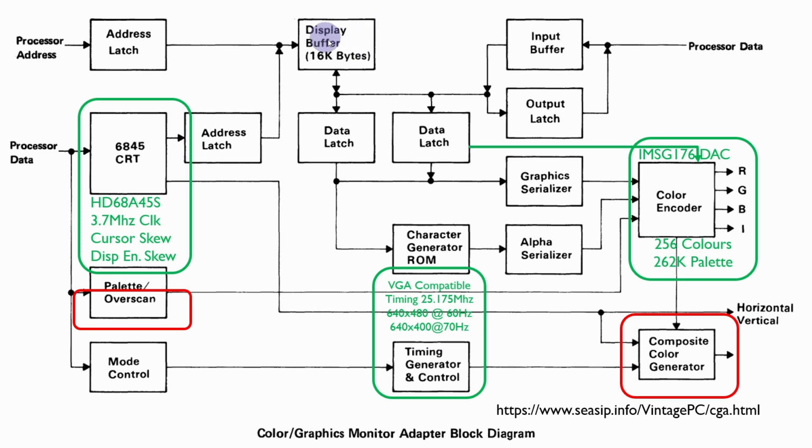So in getting the data out of the video RAM, there's two data latches. One feeds the character generator ROM, and that determines which of the 255 characters are actually shown. And then the other latch, when in text mode, you'll see here I've added this green line in here. So in text mode, this other attribute latch effectively determines what the foreground and background colors are.